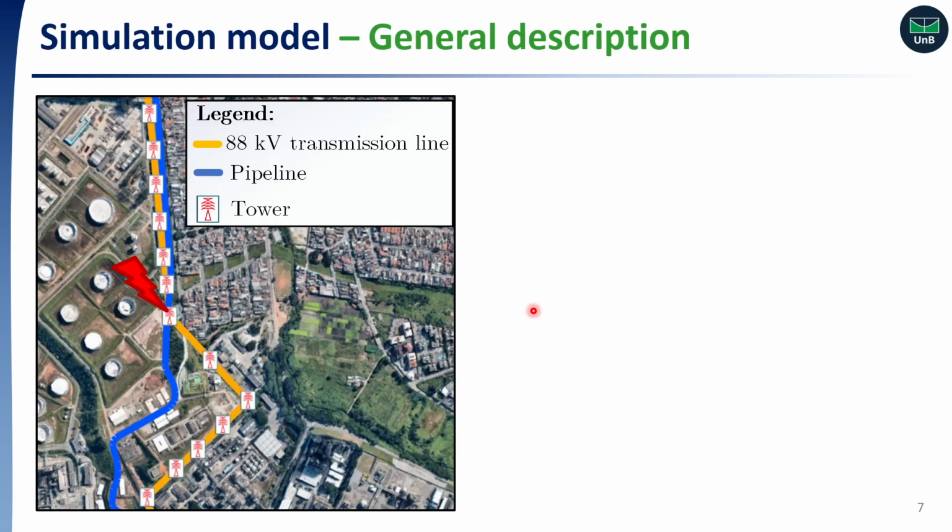So, we move on to a practical case of a shared corridor between a pipeline and a power line in Brazil. Geometry is composed of parallel sections, one crossing point, and some oblique exposures. We want to simulate a lightning discharge at the top of the tower closest to the pipeline and to see what happens with induced voltages.